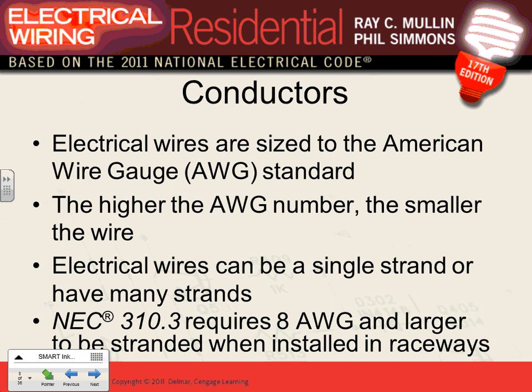And there's one little thing, you can get solid, one strand, or multiple stranded, but almost always the conductor that we use, guys, in the commercial, almost always stranded conductors. Easy to pull through the conduits. For the most part, what we use in the residential is solid conductors, typically solid conductors in the residential.